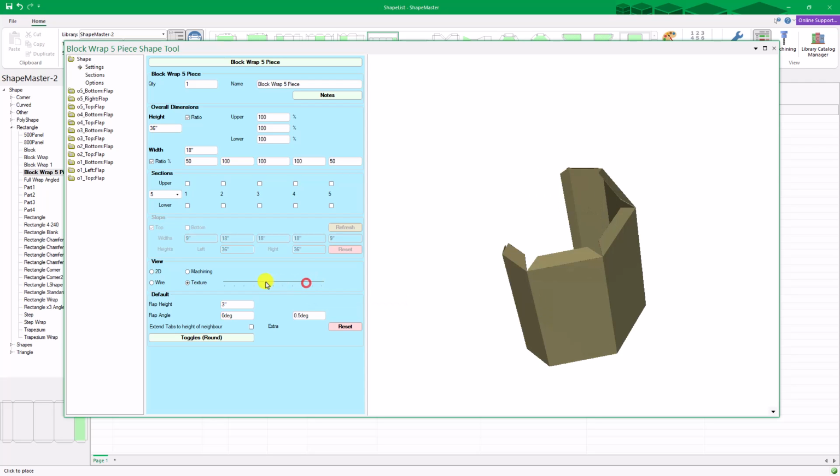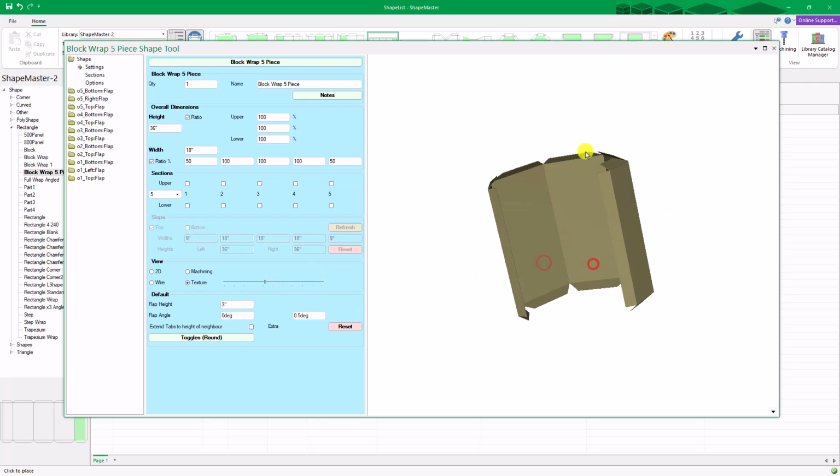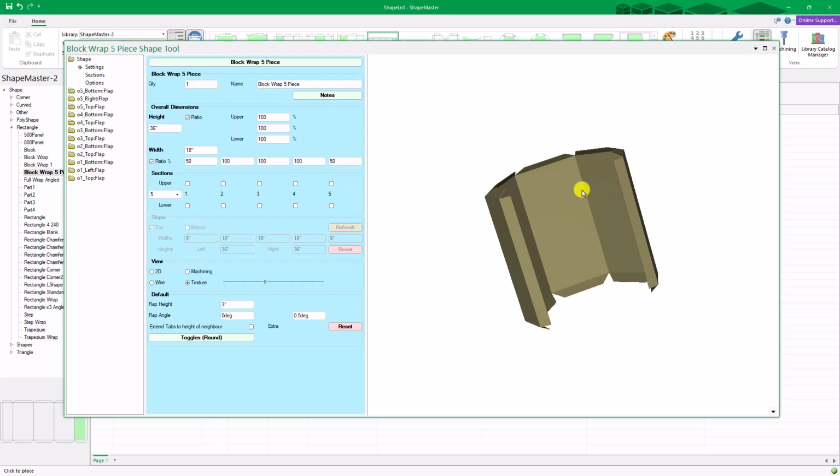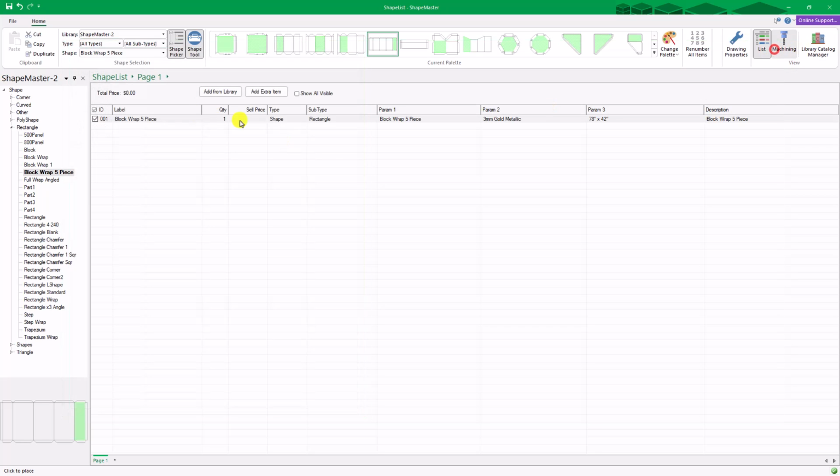You can, again, open up a little bit, see how it looks as it's folding as well, making sure things fit together. If you're happy with that, you press F12 on your keyboard, and it will add it to the list behind here. And it gives you dimensions and things, all the details about the part.